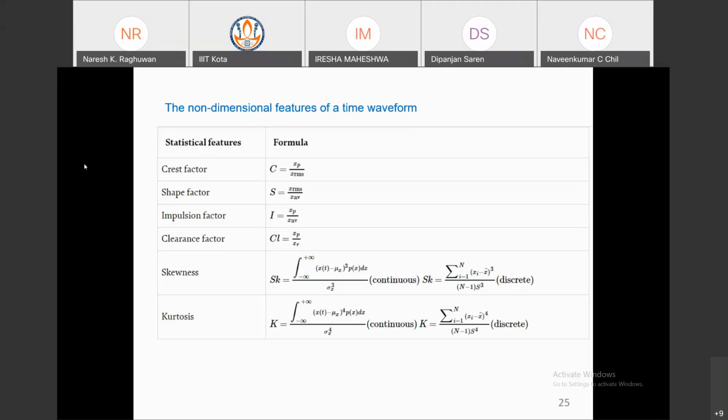So you have an indicator that if a tooth is missing, this type of signal will be there. If there is a crack in the tooth, this type of signal will be there. If there is some pitting on the tooth, this type of signal is there. So by simulation, you know this previously. After that, if you do the experiment and see that the simulation shows this type of signal is the case of a cracked gear, then the experimental and simulation results you can also compare.